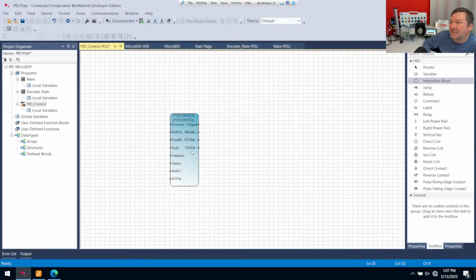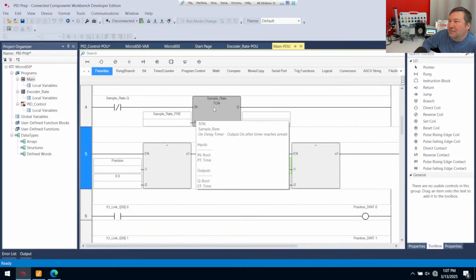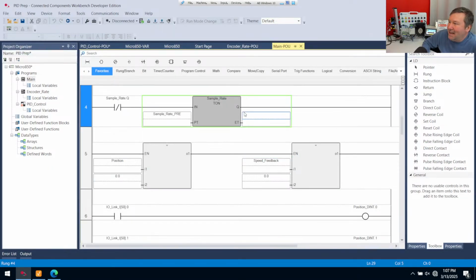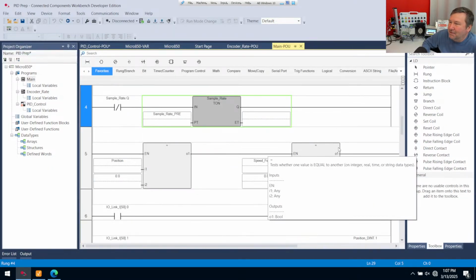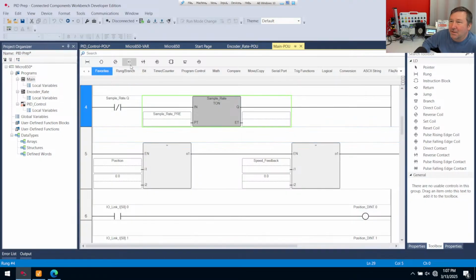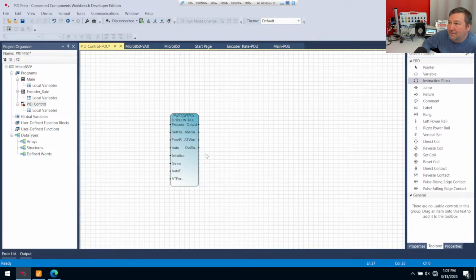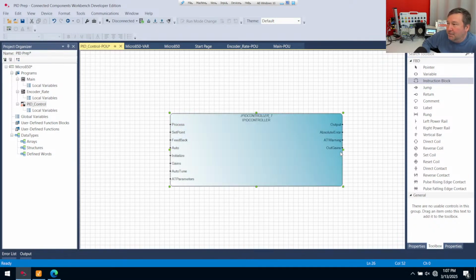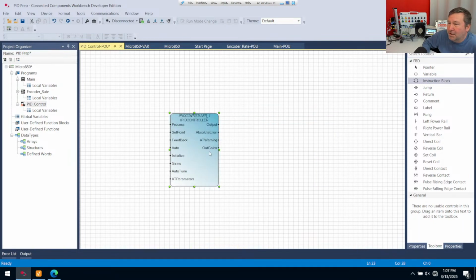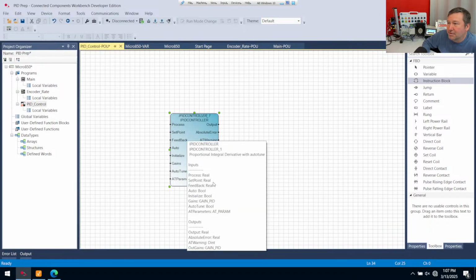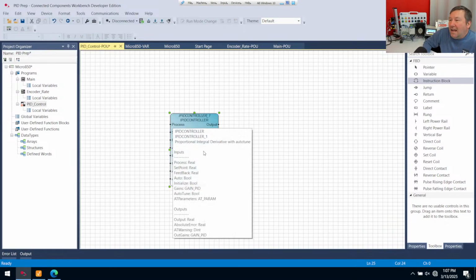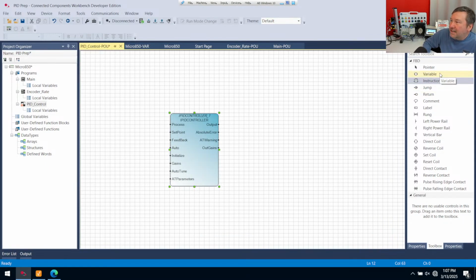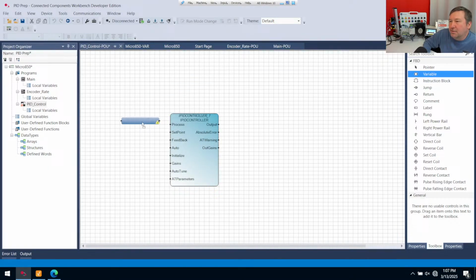We'll select it. And if you recall from our earlier video, in that one we had to widen this up and it made everything ridiculously wide. One really nice thing about working in function block diagram is I can select this and individually widen these blocks. We don't want to go ridiculously wide, but get this to where you can read all these words right here. Then we're going to start bringing in variables to create some items.